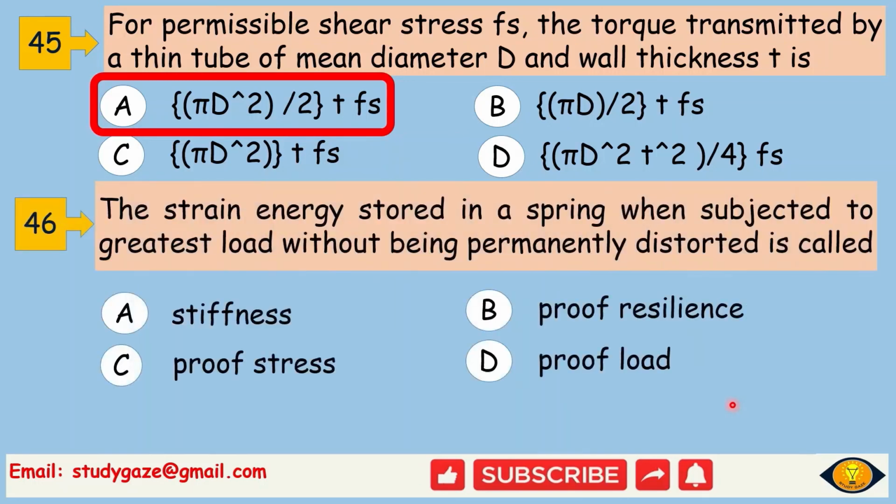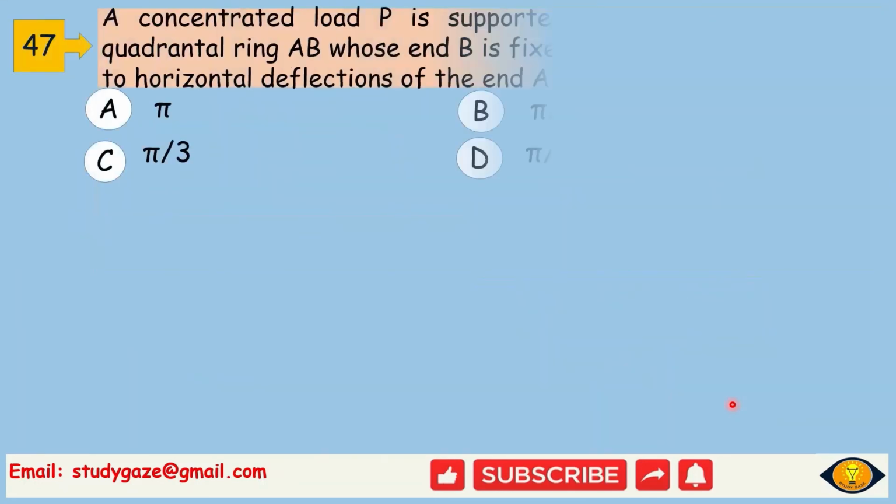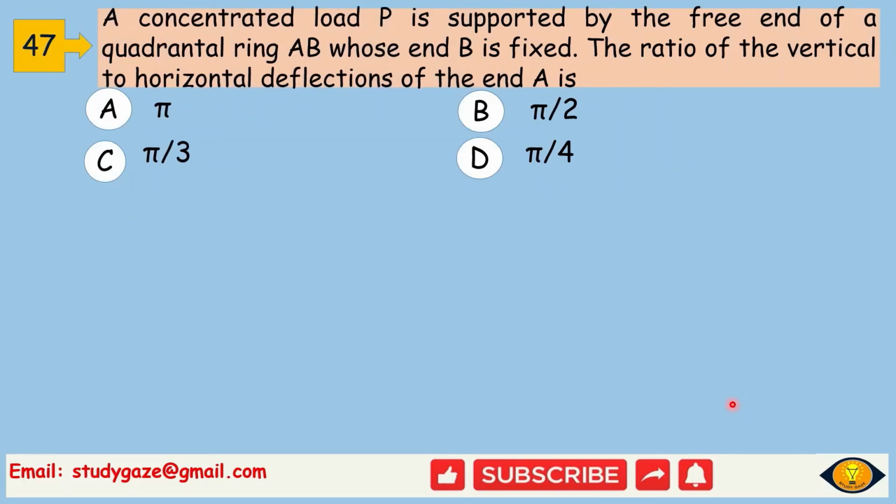Next, the strain energy stored in a spring when subjected to the greatest load without being permanently distorted is called proof resilience. Next, a concentrated load P is applied at the free end of a quadrantal ring AB whose end B is fixed. The ratio of the vertical to horizontal deflections of the end A is pi by 2.